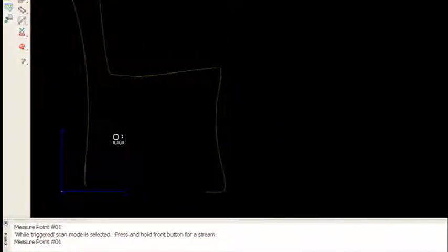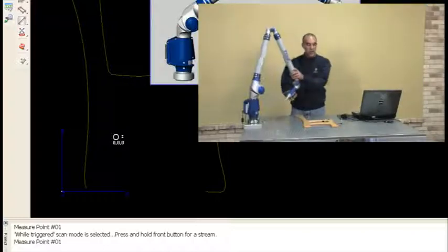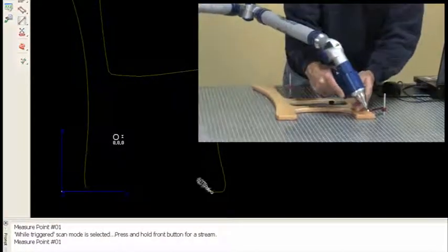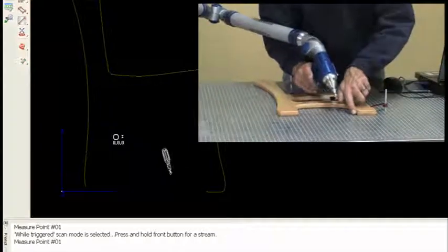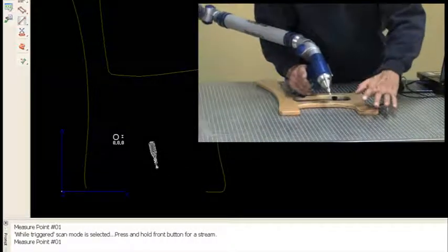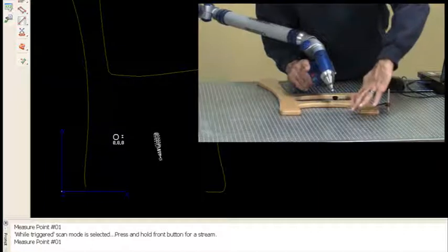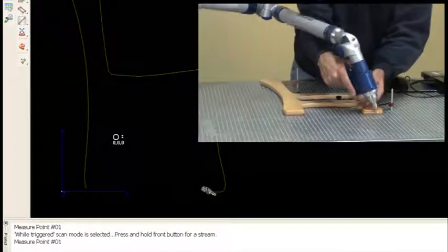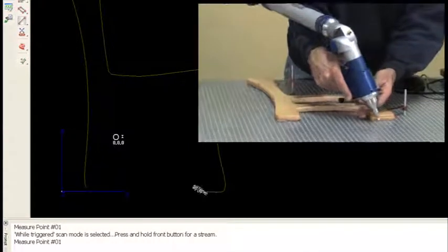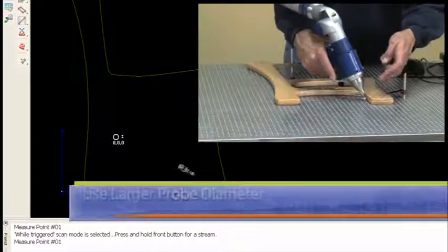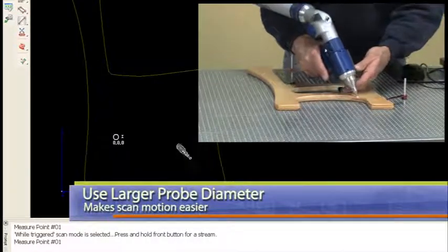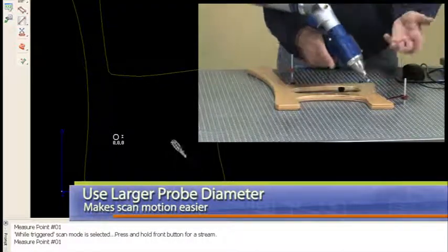Okay, so I'm set. I'm going to grab this arm now. I'm going to go right into this front area here, and I'm going to finish up the leg. And what I would do is, since this is contoured a little bit, it's maybe had a little radius to the cutter or whatever, I would probably pick up a gauge block and set this probe down into the gauge block as I tracked around the geometry, just to make sure I've got a consistent height on the scan line that I'm putting onto here. But I don't have that for this example here.